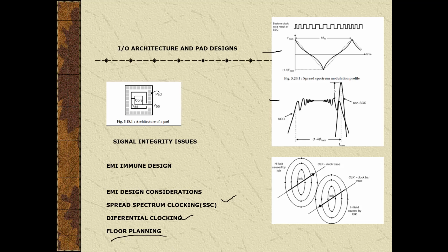This step determines the size of the die and creates the wire tracks for the placement of the standard cells. The floor planning also creates the power ground connections, and the constraints of the floor planning setup steps are to minimize chip area, make routing easier, and reduce signal delay.